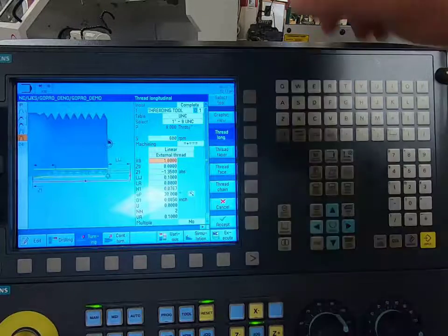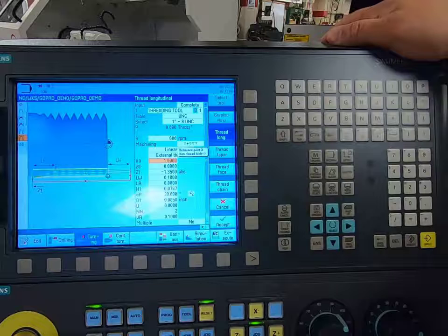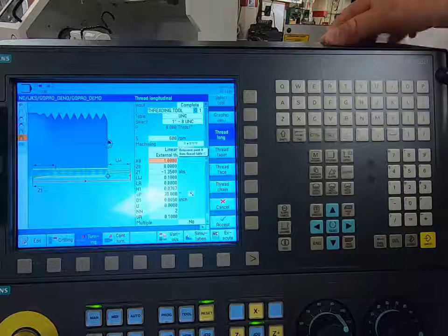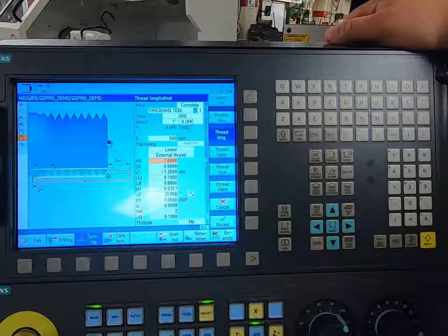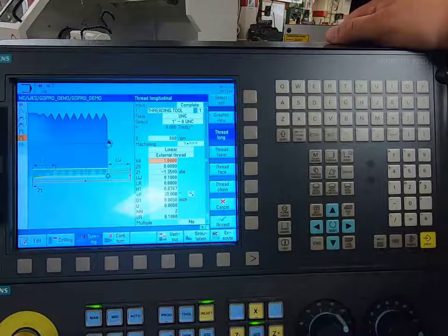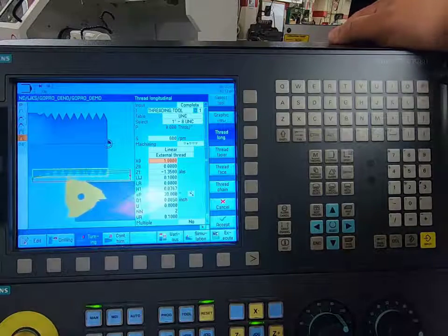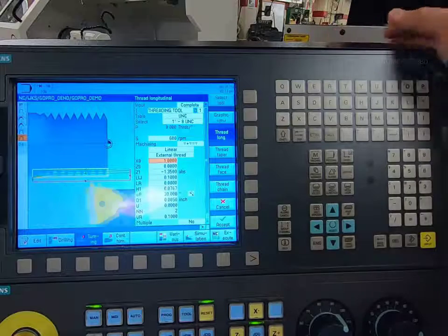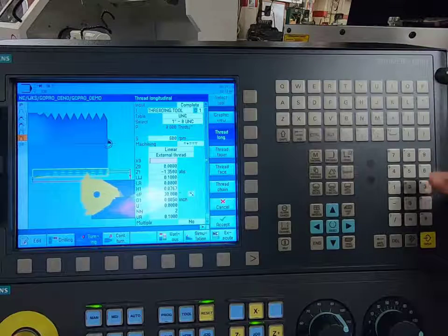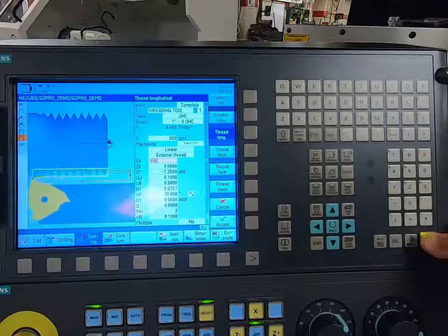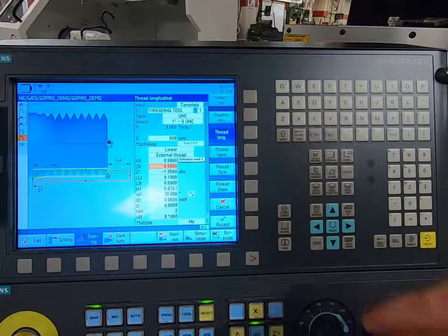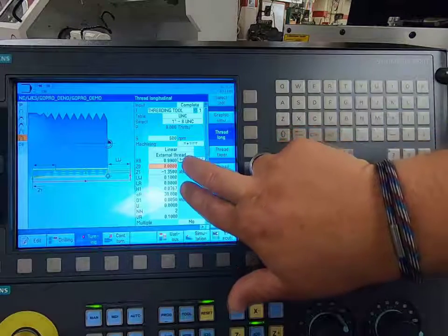I'll leave it there. Now you're going to have to look at your Machinery's Handbook and see what the diameter needs to be at its maximum condition for cutting a 1"-8 thread. So I'm going to give you a hint. 990 thousandths is right there in the middle. So I'm actually going to type in 990 thousandths. Now the reason why is, see this 76 thousandths down here?